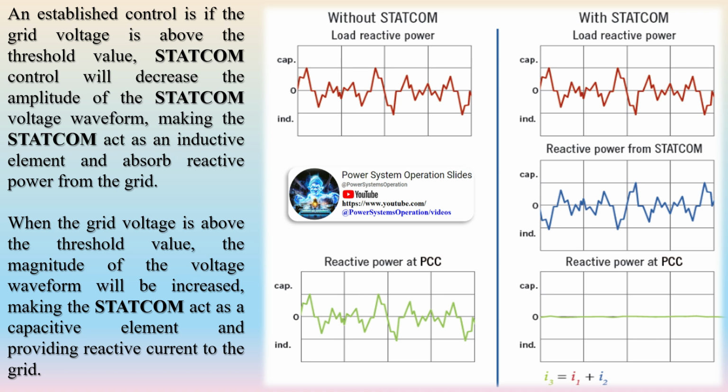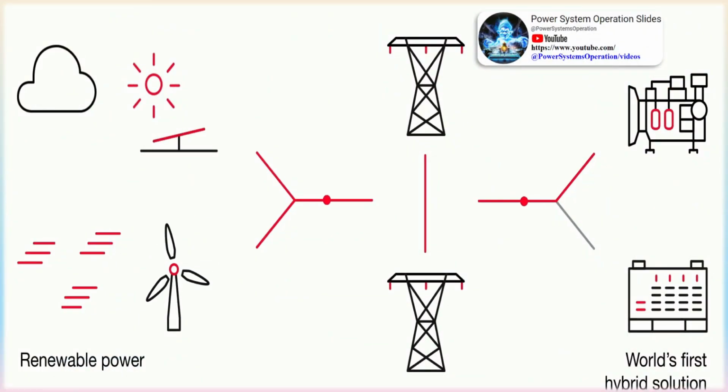By integrating an ESS with a STATCOM, STATCOM plus ESS, significant enhancements over traditional STATCOM performance can be achieved. Battery technologies offer advantages such as higher energy storage densities, greater cycling capabilities, improved reliability, and lower costs. This combined system effectively mitigates most stability and voltage fluctuation issues in the power system.